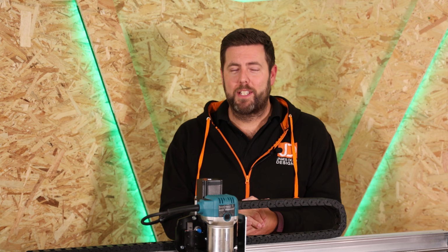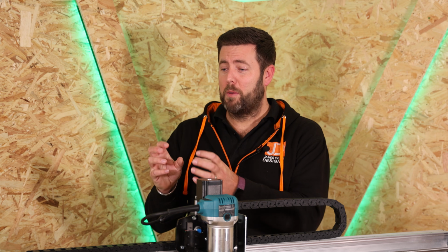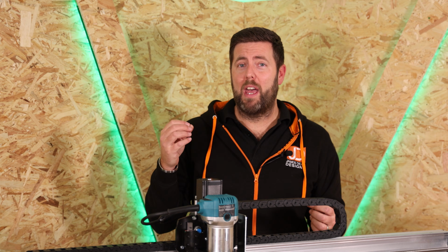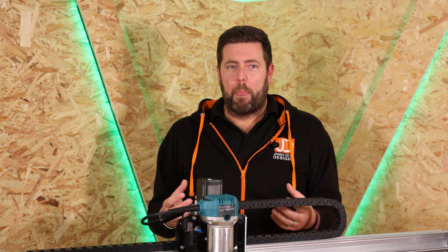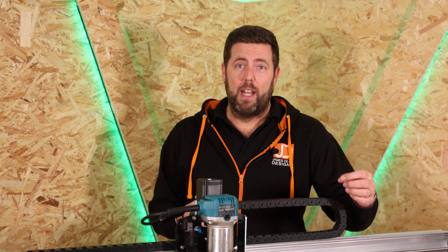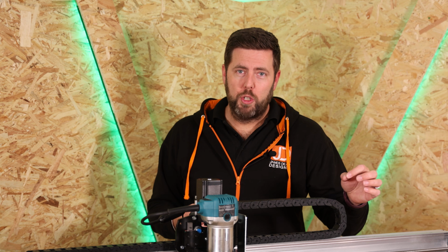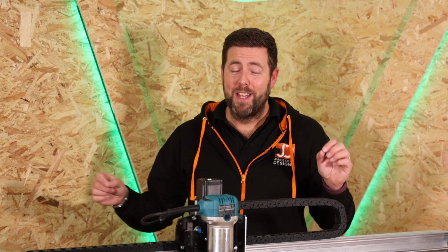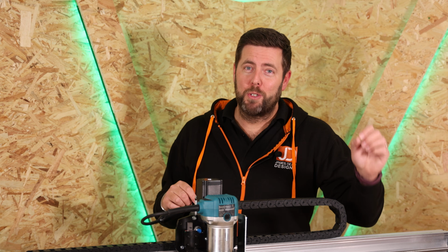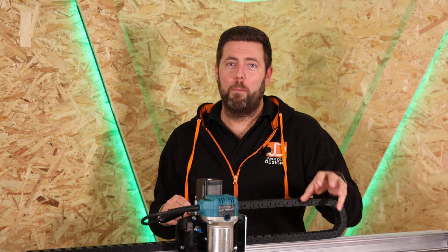Now, the reason I've left this till last is because when a lot of other people talk about it, they just go, oh, you need a good chip, and they show you a fairly decent sized chip that they're able to get off their powerful machines. Now, the problem is, if you're on something like a 3018 machine with a low powered spindle and a 1/8 bit, your wood chip is probably going to be what they consider to be dust. It doesn't necessarily mean it's a bad wood chip for that machine, and this is my point. It has to be relevant to the machine you're using.